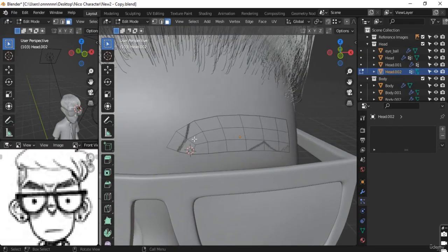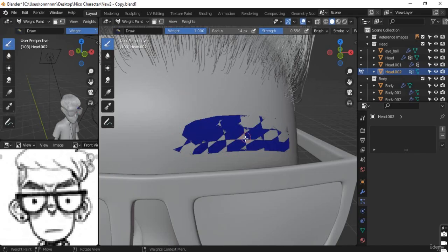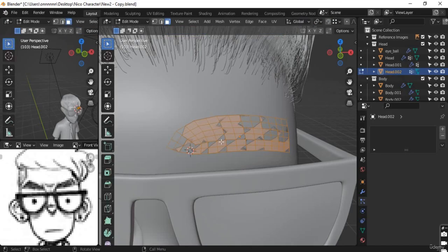I need more geometry on this surface. I need more density on this surface so that I can work with it, so that we'll have nice eyebrows. These faces are too big for eyebrows. So what I'm going to do is tap the A key, right click, and subdivide this mesh just once. Once we've done that, you can see we have a lot more dense geometry.